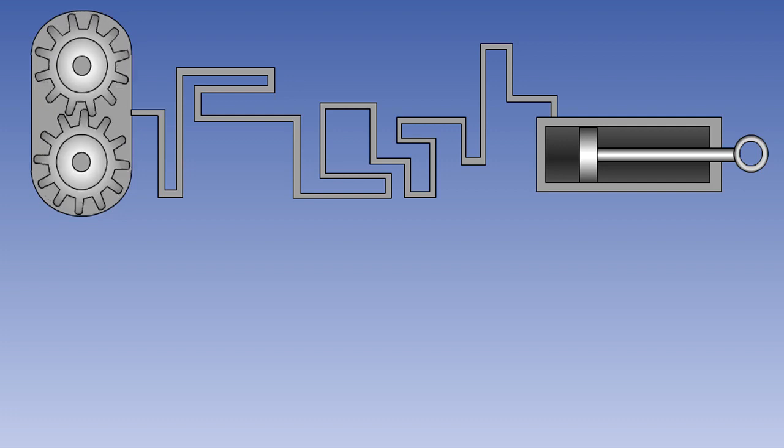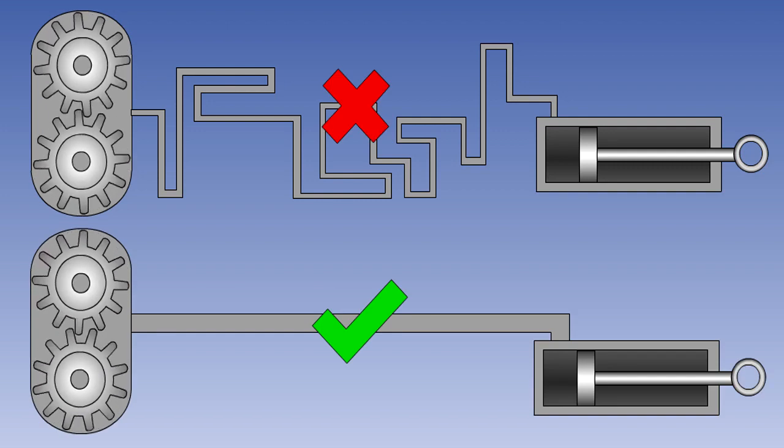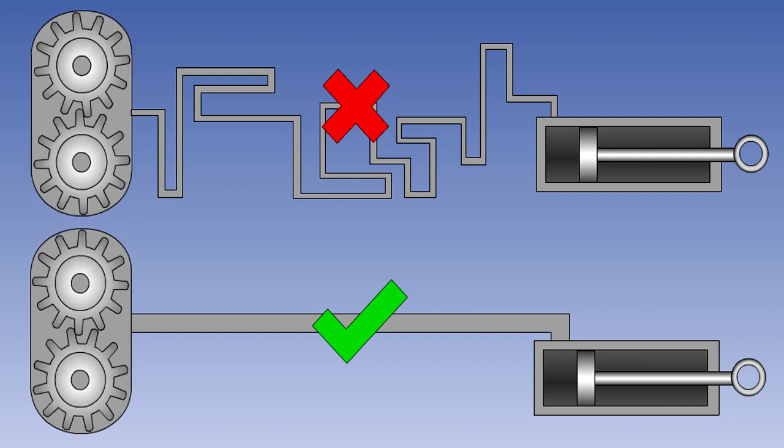The friction between the walls of the pipes and the fluid depends upon the velocity of the fluid in the pipes, the length, bore and the internal finish of the pipes, and the number of bends. Good systems are designed with pipe runs being as short, wide and straight as is practicable.